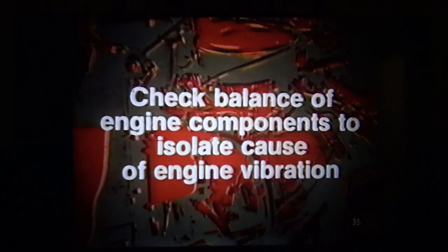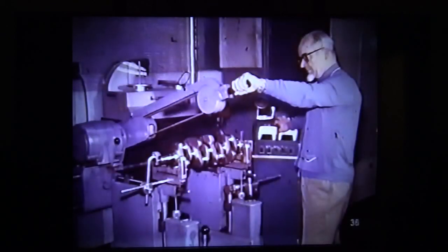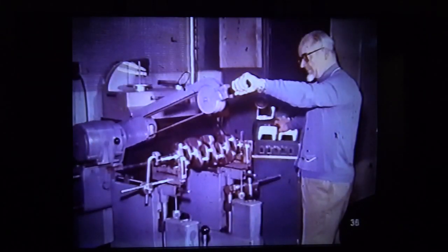If the preceding accessory checks have been performed and the vibration still exists, the problem may be the vibration dampener, crankshaft, flywheel, or clutch pressure plate. These components must be removed and tested on a dynamic balancing machine. In some applications, the vibration dampener and/or flywheel cannot be checked without the crankshaft and reciprocating bob weight assemblies. Your local dynamic balancing specialist can help you determine the best way to check the balance on the specific engine being diagnosed.